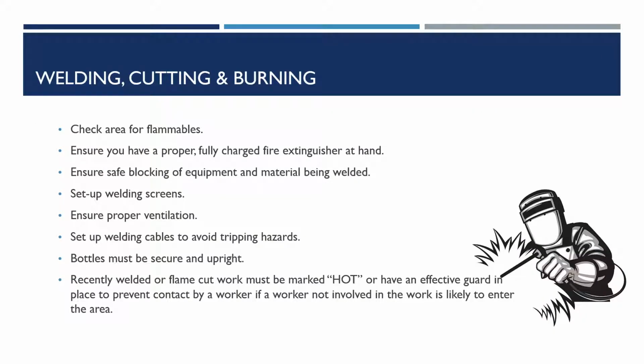Welding, cutting, and burning. Check area for flammables. Ensure you have a proper, fully charged fire extinguisher at hand. Ensure safe blocking of equipment and material being welded. Set up welding screens. Ensure proper ventilation. Set up welding cables to avoid tripping hazards. Bottles must be secure and upright. Recently welded or flame cut work must be marked hot or have an effective guard in place to prevent contact by a worker if a worker not involved in the work is likely to enter the area.